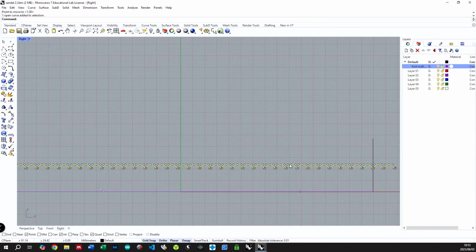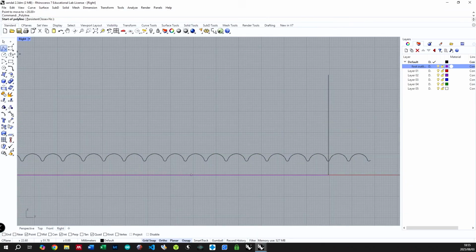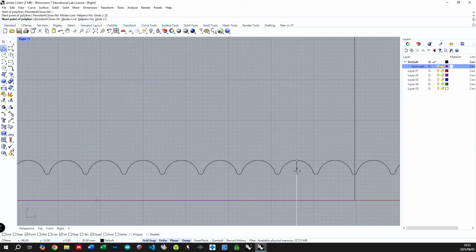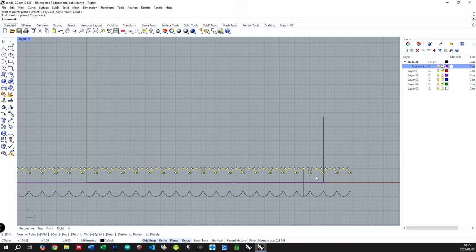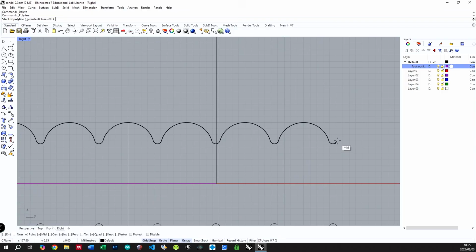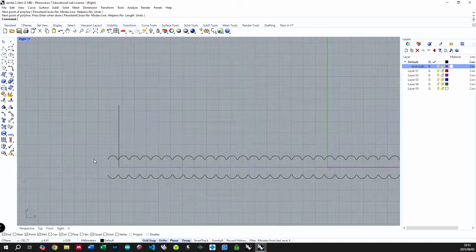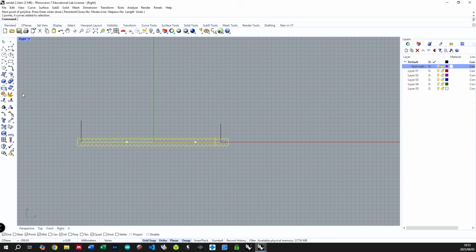All right, so next up, I'm going to move that downwards to around where our sole should be, and I want my sole to be about 20mm thick, so I'm drawing a line that is 20mm long to there, grabbing that and saying mirror to the opposite side. Where's my midpoint? I'm just turning on my mid snap and flipping it over to that side, and I'm drawing a line to connect the top and the bottom curves. No, that's not right. From the end, just turn on my end snap there, from the end to the end, and then another one over here from the end to the end, and we join those together, join.